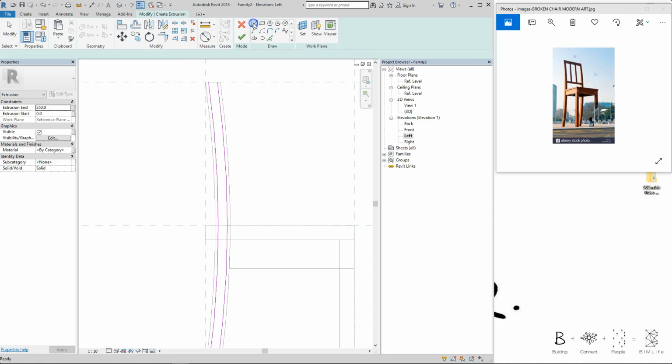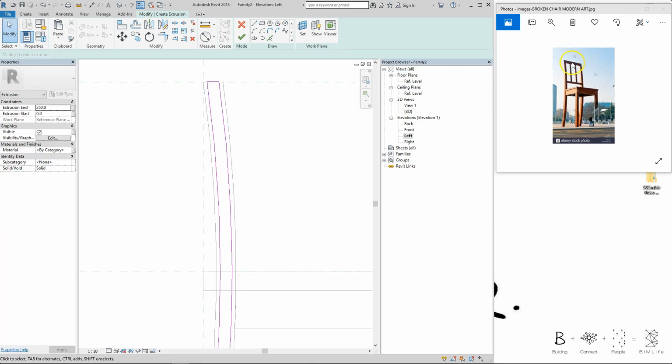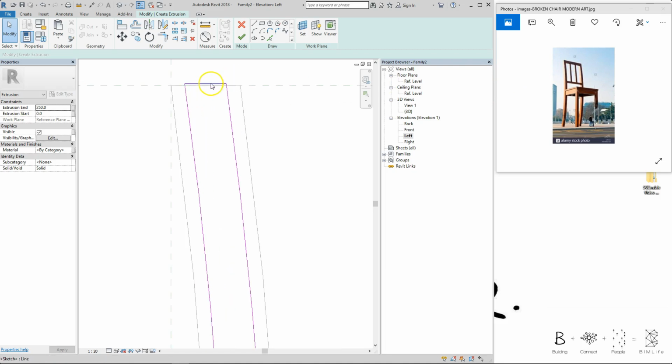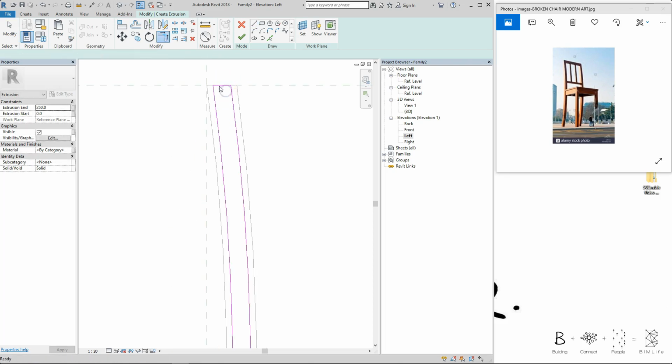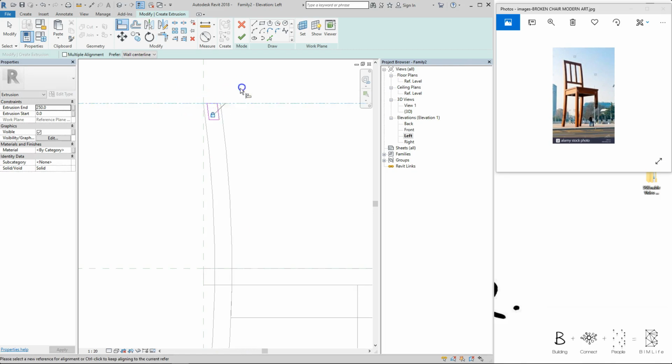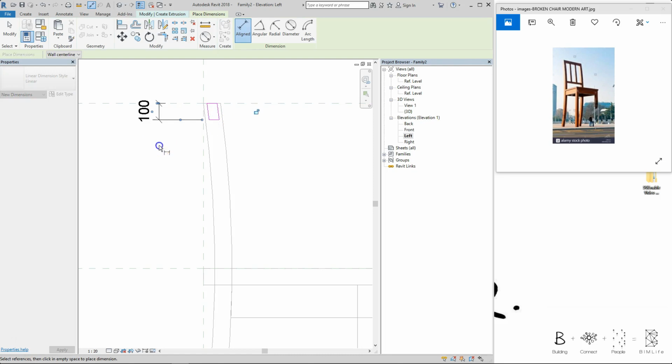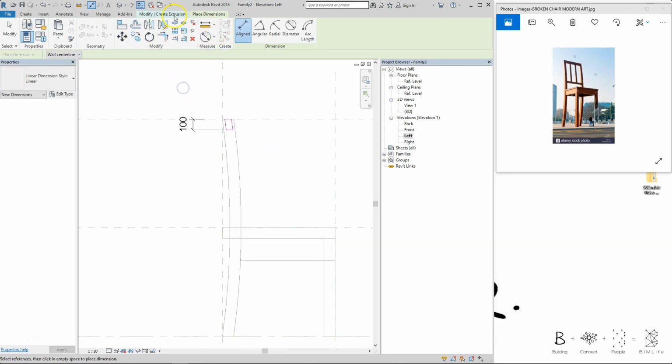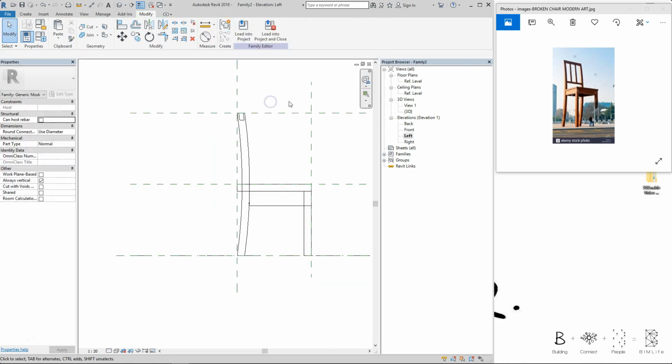Afterwards, I'll just draw a normal line. Just make this offset 0, otherwise you can't draw. So just set it here, and then I'm just going to make the thickness of this back support 100. So I'm just going to copy it down. Oh, sorry, this is rotate. Oops, copy down by 100, and use the trim command to fix all this. Afterwards, remember to align. So this will follow the top, and reference plane to the bottom sketch. Make sure it's locked at 100, and press the green tick.